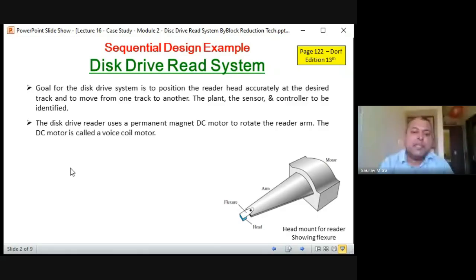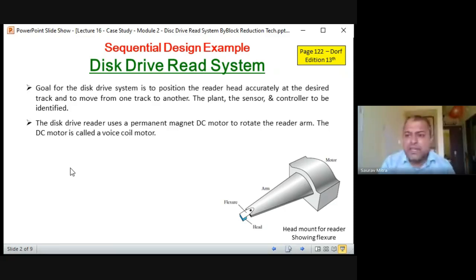So whatever electricity is being given to the DC motor, it does two things. First, it supplies the current to the armature conductor, that is this middle finger, this is the input. Second, which is the main thing I was going to explain, it creates an electromagnet inside the motor. So that electromagnet produces a magnetic field, MMF. So two things are created inside the motor after we supply electricity to the motor.